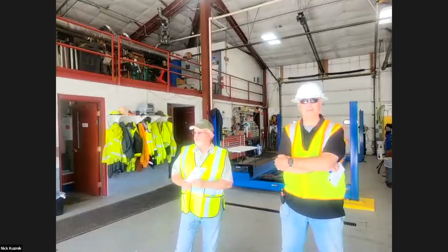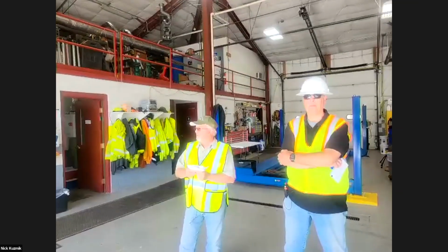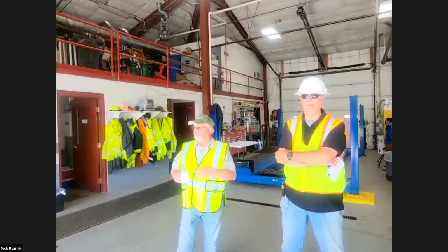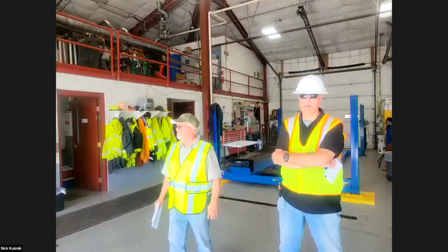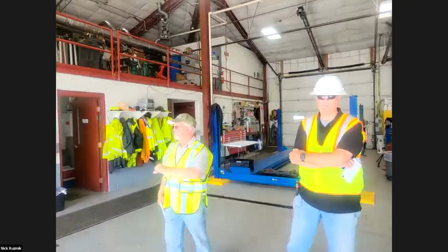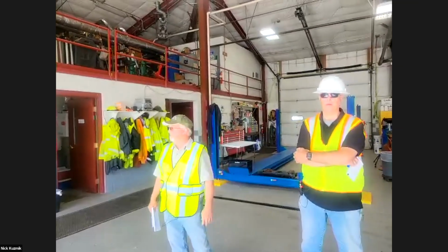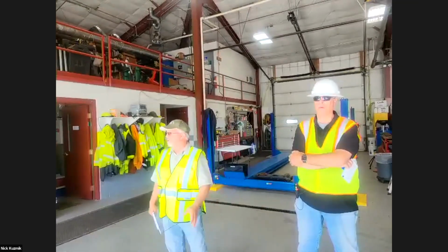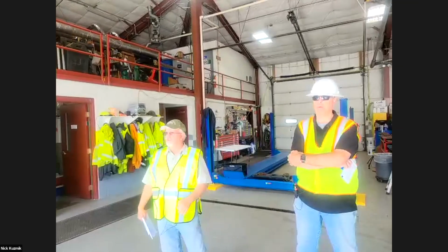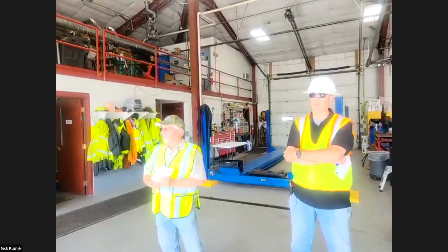Okay. Yeah, you don't want to start with the signs. You don't want to start with the paper. So you want to start technically where the traffic is, the opposite end of where the traffic's coming, and work in reverse as you would have set it up. Again, you want to protect your workers and the people pulling the signs out. So the last cones you would pull out would be the cones facing the oncoming traffic at that paper, right near where the flagger would be standing.